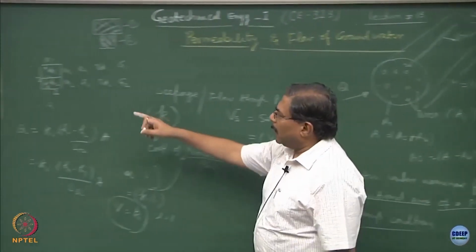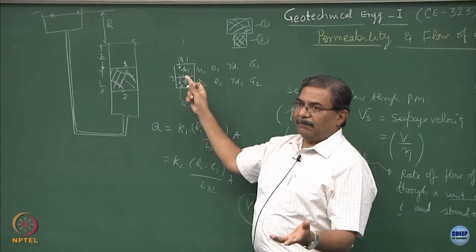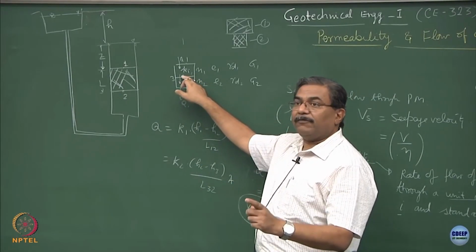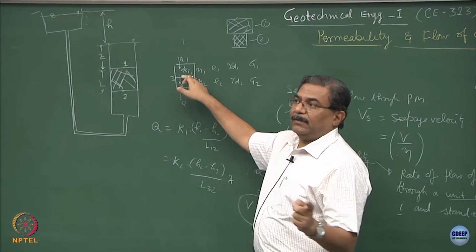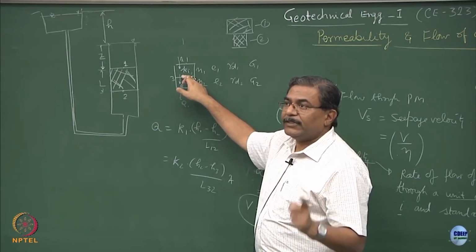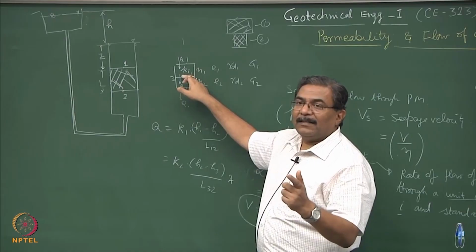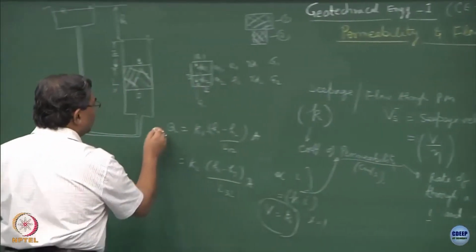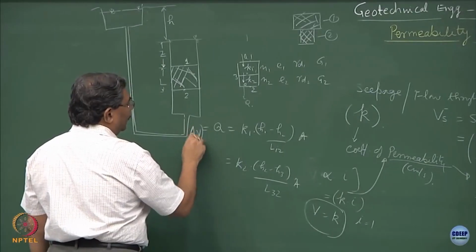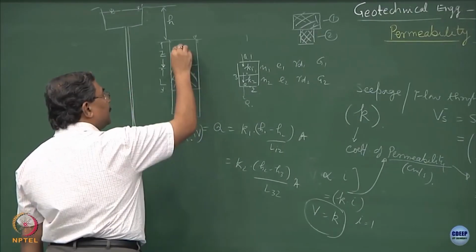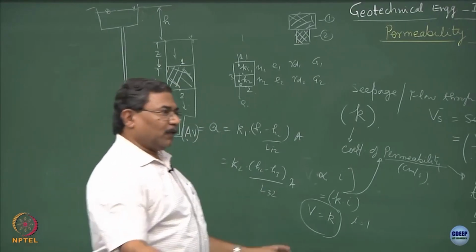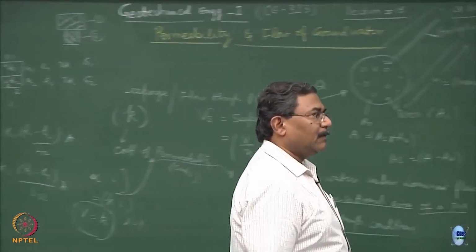As far as the total head and pressure heads are concerned, they remain the same. The only thing is, now you are introducing a point at which the state of energy is not known, which can be solved by using the continuity principle. So this Q is nothing but A into V. This V is here and this V is here also, that is it. Is this okay? Concept clear?